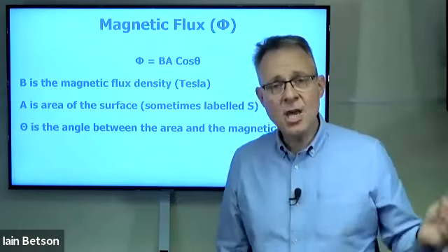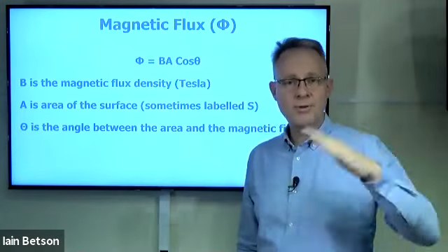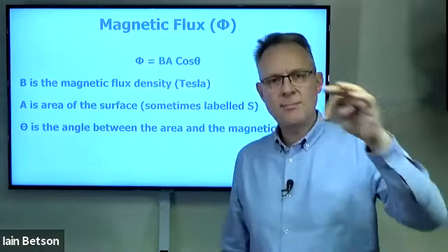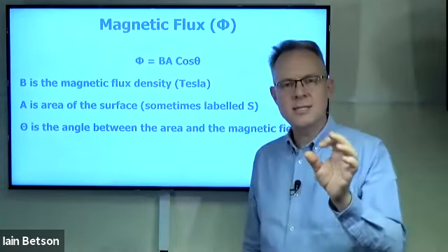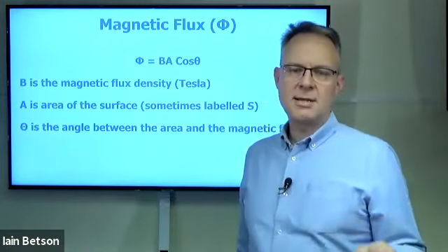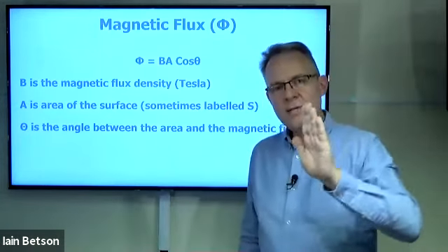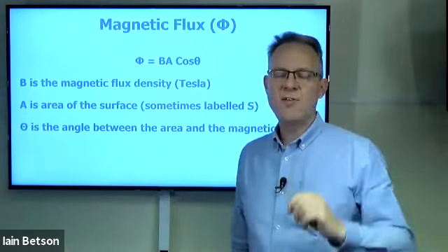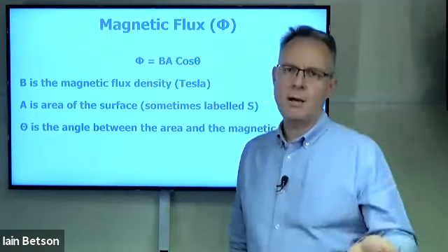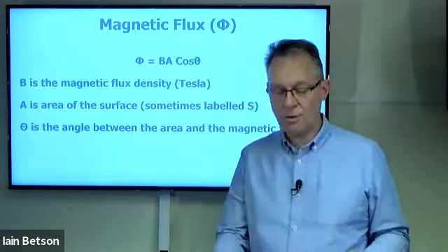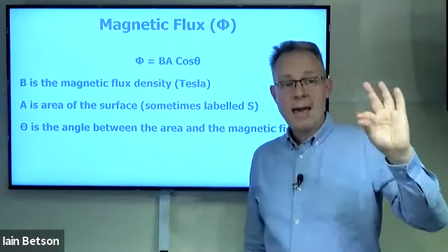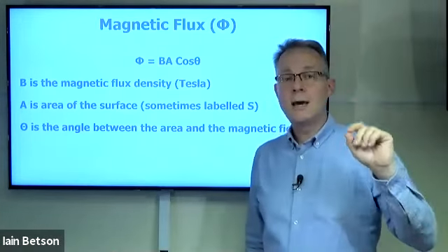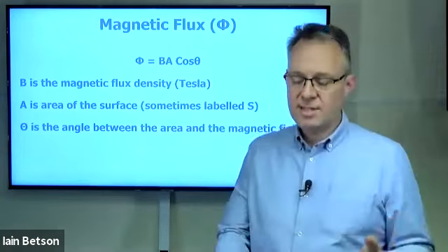start getting dirty heads, your high frequencies start to go down, because effectively, to use a rather crude term, they can't jump across the gap between the magnetic head and into the tape, and therefore magnetize the particles. Or if your head is misaligned, that is where your angle will change, and therefore the amount of magnetic flux imparted into our head goes down. So two terms there, our area and our angle, or our cosine theta, has a bearing on our everyday tape use.